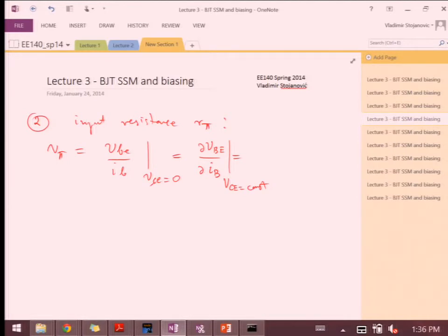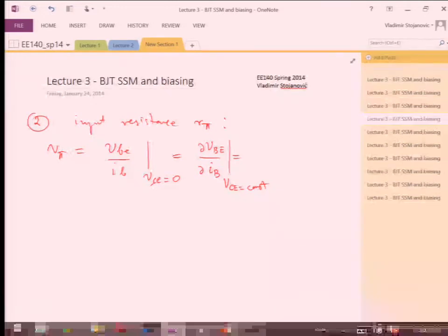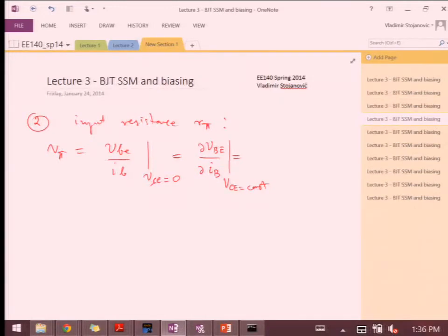But normally, if you do change that reverse bias junction, you're changing the slope and the total amount of carriers in the base. So you are affecting some base current things like recombination current that we talked about. And so there is a sort of side channel to attacking this number.